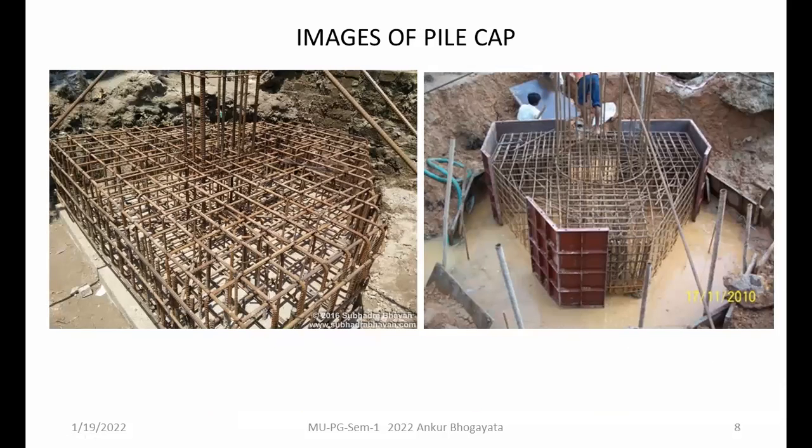This is, I would call, a complete pile cap. You can see the amount of reinforcement that is provided. Tremendous reinforcement, very closely placed reinforcement is provided in all directions, like top, bottom, vertical and horizontal. So it's a box like structure, pad like structure. And on the right hand side, you can see some additional steel is being provided just to reduce stress.